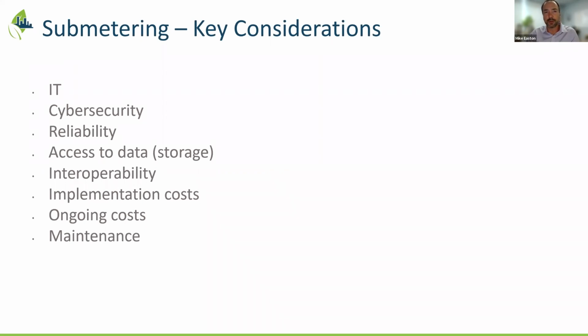We talked a bit about communication challenges as well. If you're not getting data out of your meters, they're really irrelevant to your building automation system or your energy management system. So ensuring that there's constant communication with the meter is really critical, and that can fail for a variety of reasons. You can have somebody sever a hardwired connection into a meter. You can have other connectivity issues, somebody changes some networking or programming.